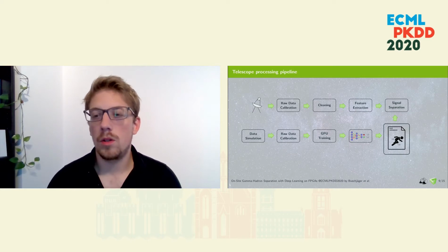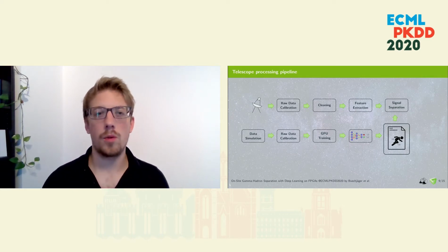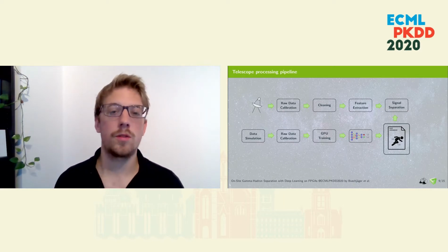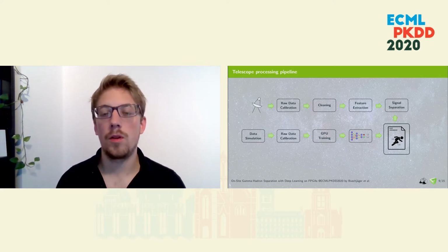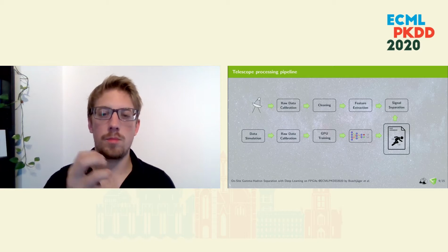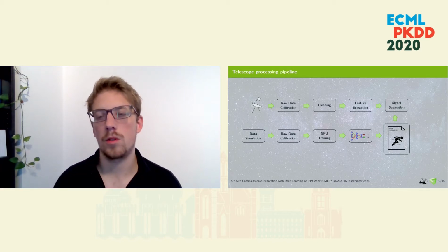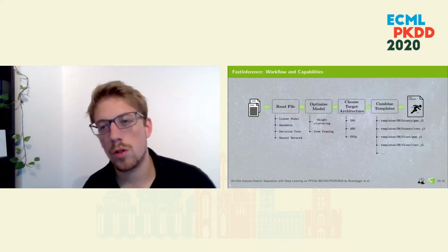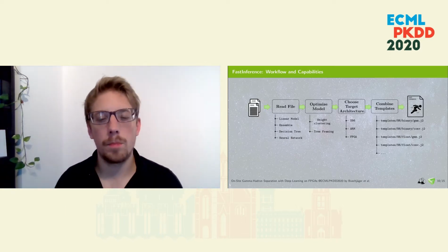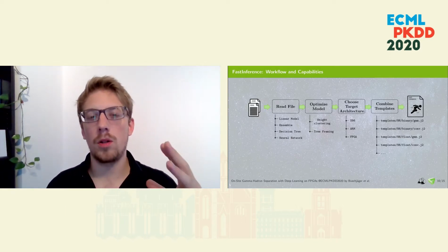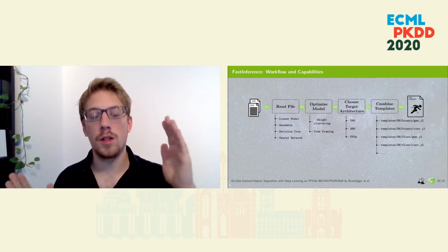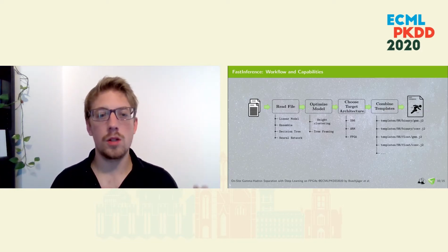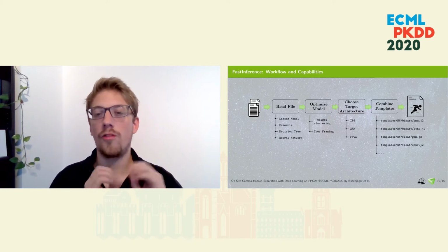Then we looked at how to utilize those special types of networks, and there are a couple of inference engines out there which perform a very efficient forward pass for deep learning models. However, we couldn't find any utilizing the special structure of binarized neural networks, so having +1 or -1 and using pop count and XOR efficiently. So we came up with our own solution, and just to quickly give you an overview, the basic idea is to take the model and unroll it into its entire C code. So just read it and generate the code and all the weights into one file.